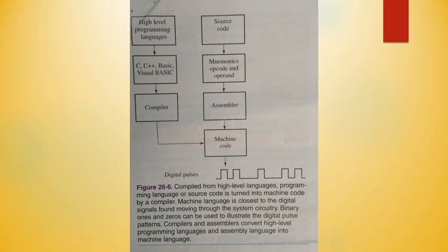One language that can be used to program a microcontroller is machine language. Machine language, or machine code, is a computer language constructed of ones and zeros that represent binary codes and digital value or digital pulse levels. The computer understands machine code without further conversion. There is no form of code that is closer to the machine itself, hence the name machine code. Machine code is also referred to as object code or executable code.